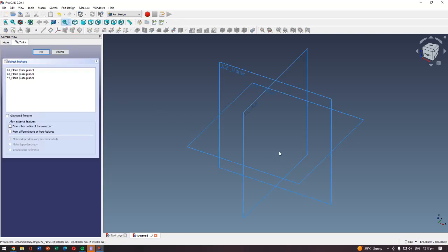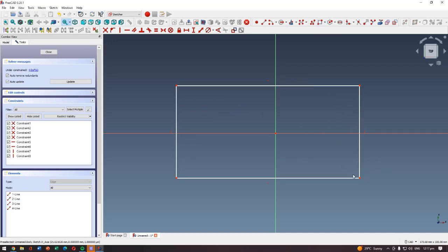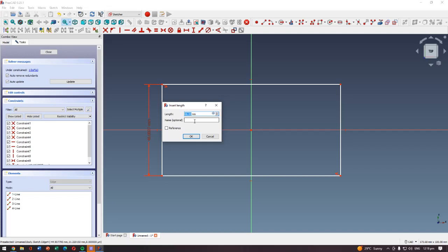Here we can select from three different planes, depending on the orientation of the duct. So for simplicity purposes, we will choose the XY plane. Then we have to start by creating a rectangle. I like to constrain the rectangle with the origin so that it will always be symmetrical, and when you try to put it together in A2plus, the origin is always at the center.